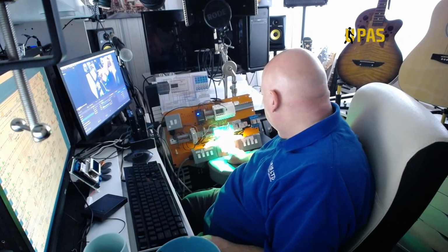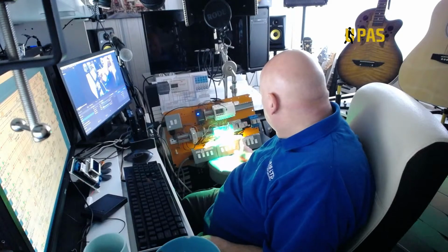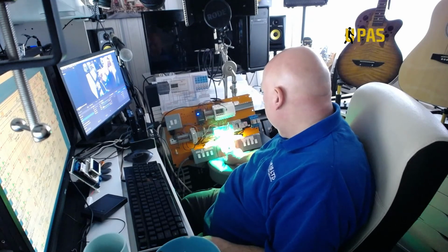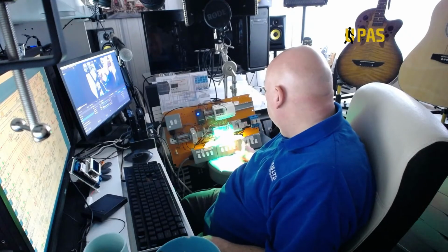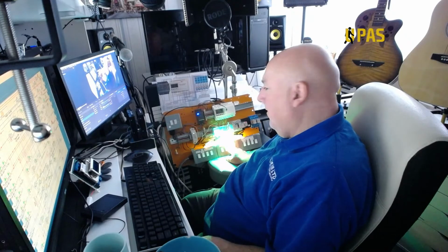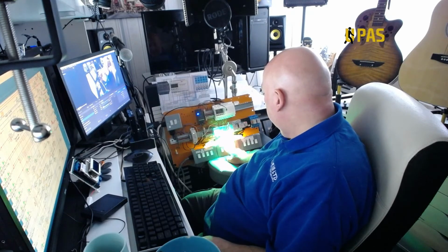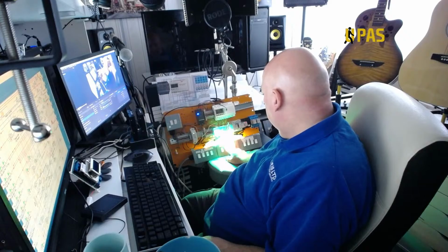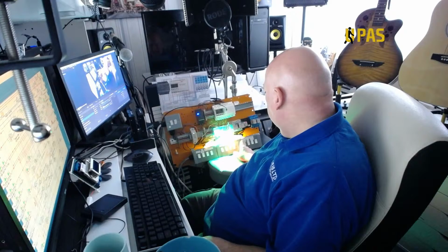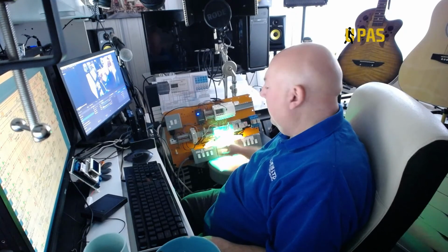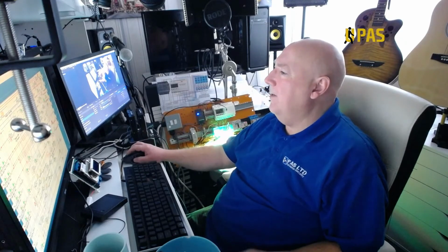So I need to make the ped gate, when you're in crashed out mode, it's only when you're in crashed out mode, I think. The laser, once you clear of that, it's got to look at the gates being shut. But no, if the gate's open, it holds the mag lock off from locking. All this is done in the normal sequence without being crashed out. It's fine, but I need to do it when we're in the crashed out mode, so not lock that gate until the area's clear and both gates are shut, then lock the gate. So it shouldn't take much to sort that out, so we're going to sort that bit out now.